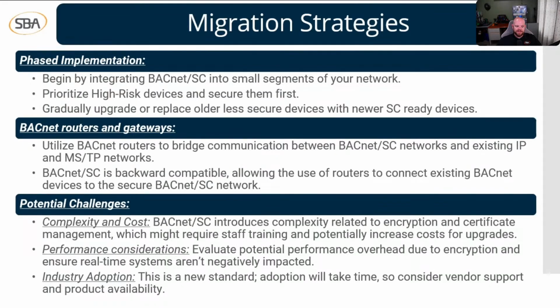Next thing we're going to look at is BACnet routers and gateways. So we would use BACnet routers to bridge communication between BACnet SC networks and existing IP and MSTP networks. So this is talking about taking a router to have all of our different comm protocols talk together on the same network. So that would be Secure Connect, IP devices, and MSTP devices.